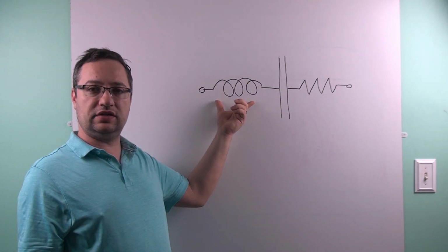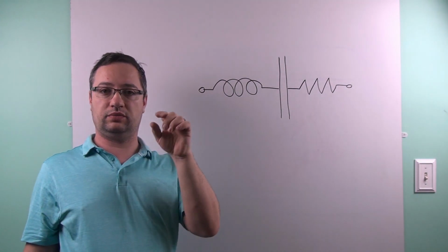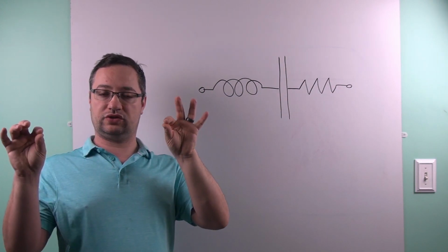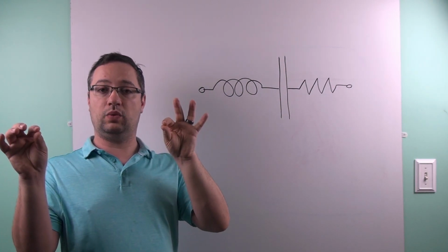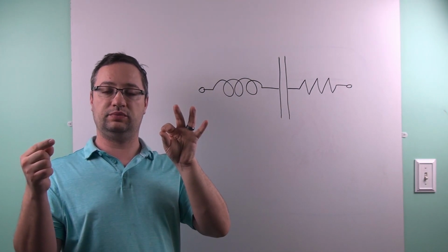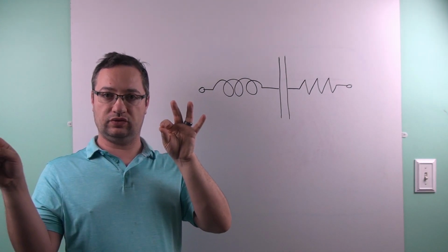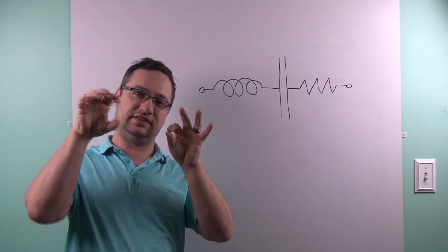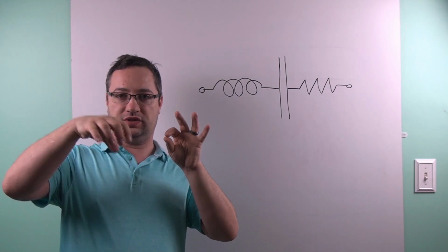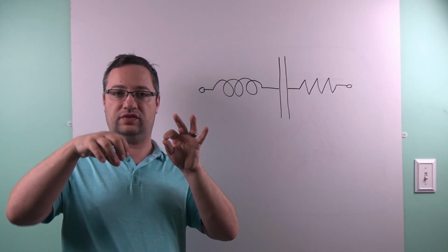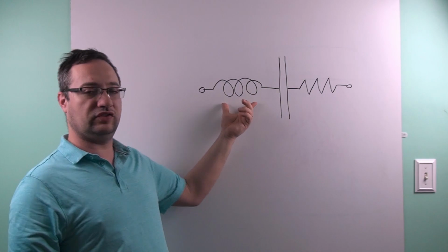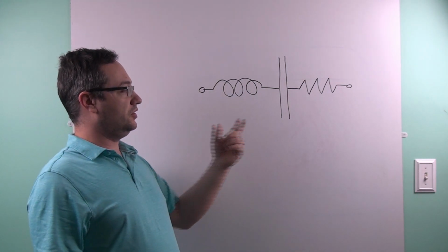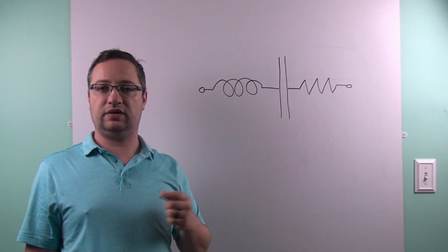Then you have an inductor. The inductor here comes from, again, the fact that the capacitor has leads. Whenever you get a single strand of wire, that wire has some amount of inductance, because as current flows through that wire, a flux basically sets up around that wire and forms a magnetic field, and that magnetic field is what effectively causes your inductance.